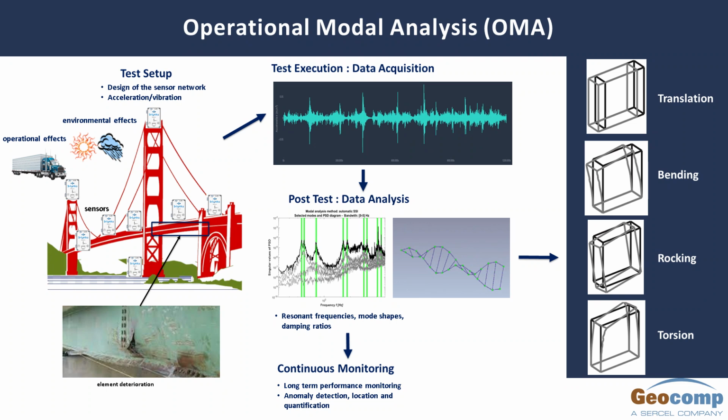In terms of operational modal analysis, we don't have a very easy way of measuring the inputs, so we are only looking at outputs. Output meaning the structural response to all those external activities. What you're seeing on the top middle section of this slide is a typical vibration signature from one of the locations on the bridge. And then by combining all the measured spots on the bridge, we identify all the peak frequencies that are inherent to the structure.